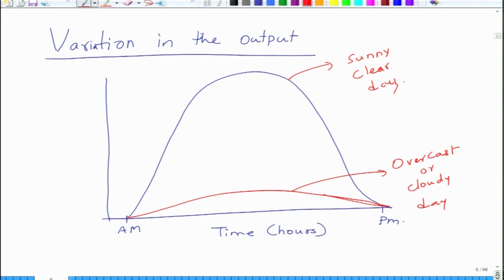So, there is a huge difference, and this is for a given certain tilt angle and so on and so forth. This is for a solar surface, the amount of energy that is incident, which is going to determine the output current, let us say, from a solar panel. So, there is a huge difference in the output. This is substantial. How much output your solar cell is going to produce depends upon the sky condition or the cloud condition on that particular day.